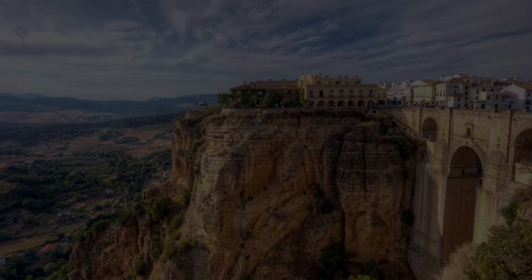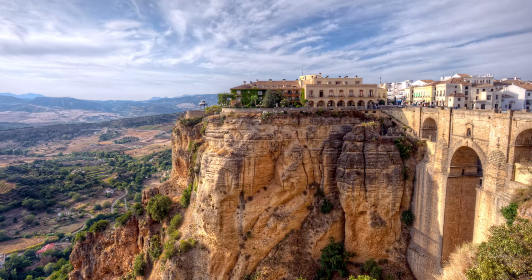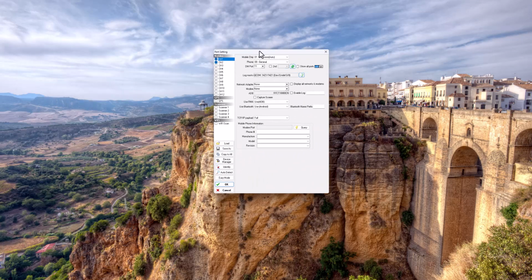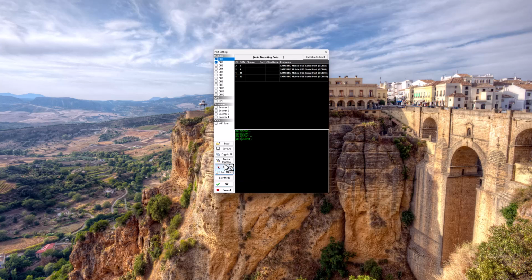The first thing you're going to get is this dialog. Just click yes. The first pop-up you will see is this one right here, the port settings pop-up. This is where we are going to configure LML, basically let LML know what we just plugged in. A good place to start is to hit this auto detect button, and you should see it go through and look at those COM ports. These are the COM ports we just saw in the device manager, and it will automatically figure out the chipset and which of the COM ports to connect to.